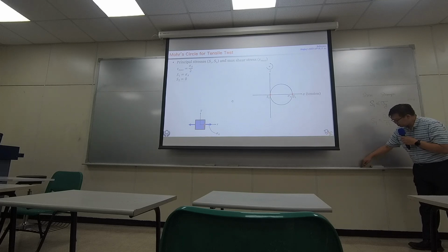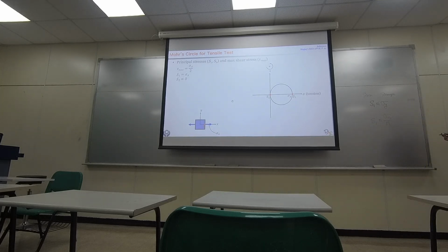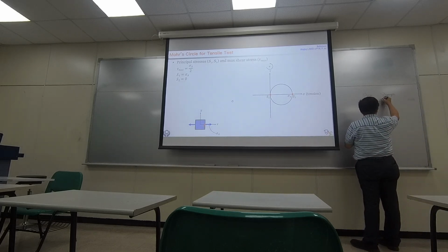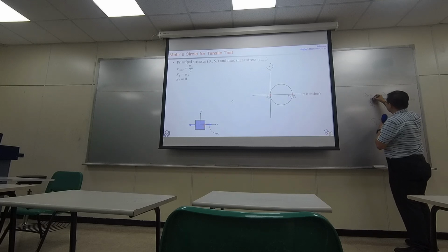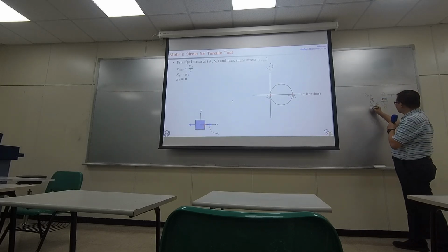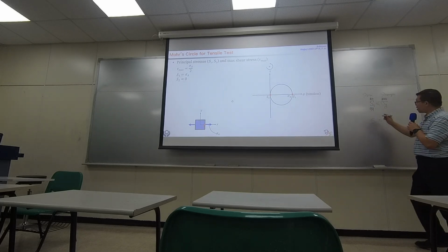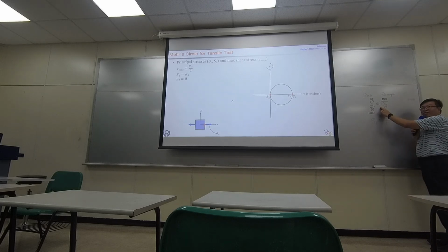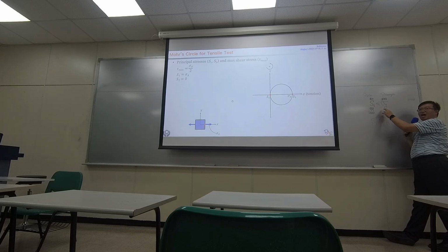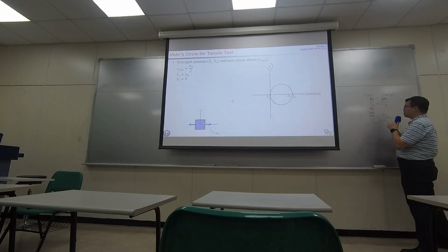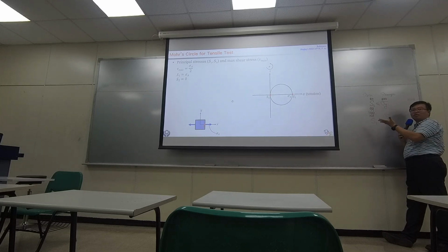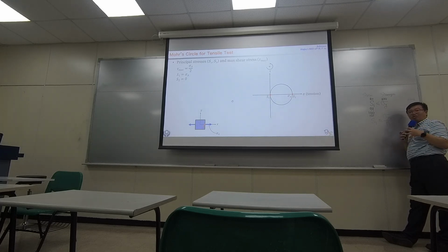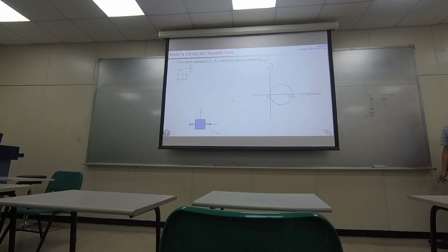Why is that? If I put in some numbers, you can observe this more easily. Let's say the strength of the material is 100. When I carry a stress of, for example, 80, I'm safe. If I carry 99, I'm safe. If I carry 100, then I am about to fail because the stress I'm carrying is already reaching the upper limit. If the stress increases by one unit, then the stress is larger than the strength. I should see a yielding condition. Then the material will be nonlinearly deformed. It doesn't recover back to its own shape. So we don't want to see this situation happen.